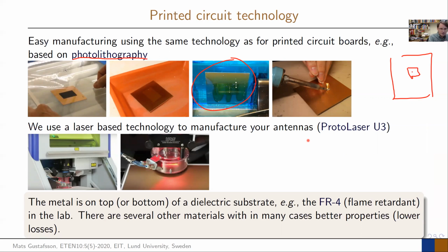And then the metal there would stay, the rest will be removed. And that is the reason when this was drawn, you basically made this entire black here, and that is what we kept. And then afterwards, you can solder here an SMA connector to your patch, and that you will also get to your patch. And then you could get an antenna that basically looks like here from the back.